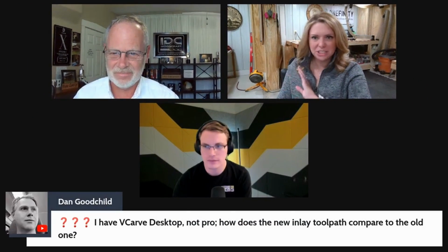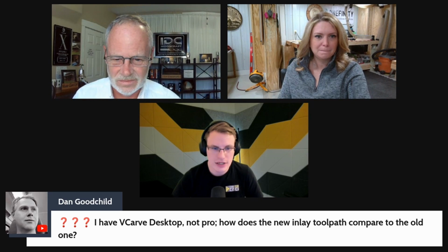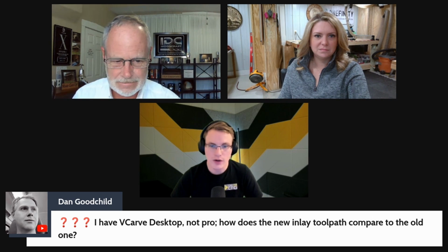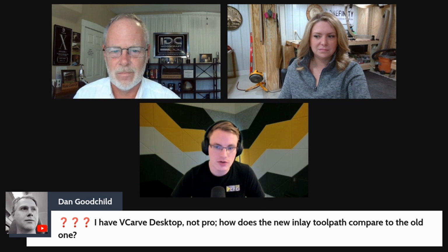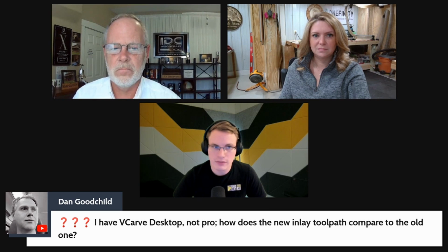Oh my gosh. Okay, so I think we briefly touched on this, but I want to bring it up in case somebody missed the conversation a little bit. Yes, so he says he has VCarve Desktop, not Pro. How does the new Inlay toolpath compare to the old one? Well, the old one that he's referring to is just a 2D inlay toolpath. The new toolpath is a VCarve inlay toolpath. So it's a completely different method of inlays.